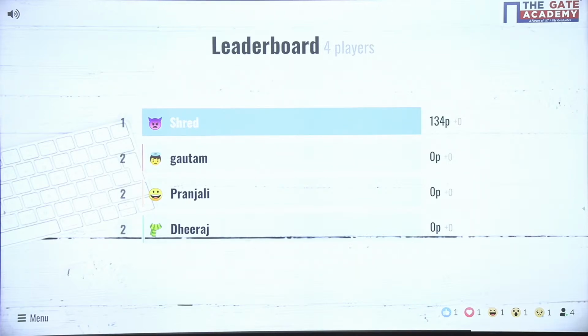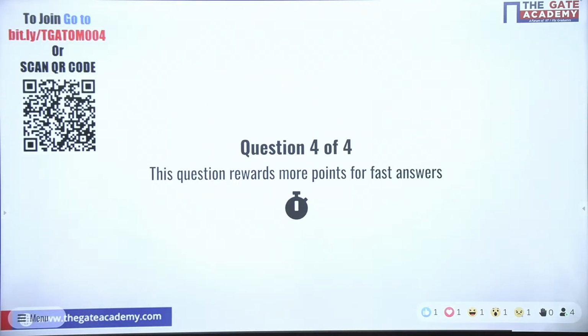So I see none of you could completely answer it. So remember secondary forces. If you remember, what are the secondary forces? m r ω² cos 2θ / n, right? This is how we can relate it with the primary. And if all the masses are in the same plane, we can balance it by a single mass only. Okay, now coming to the last question for the quiz.